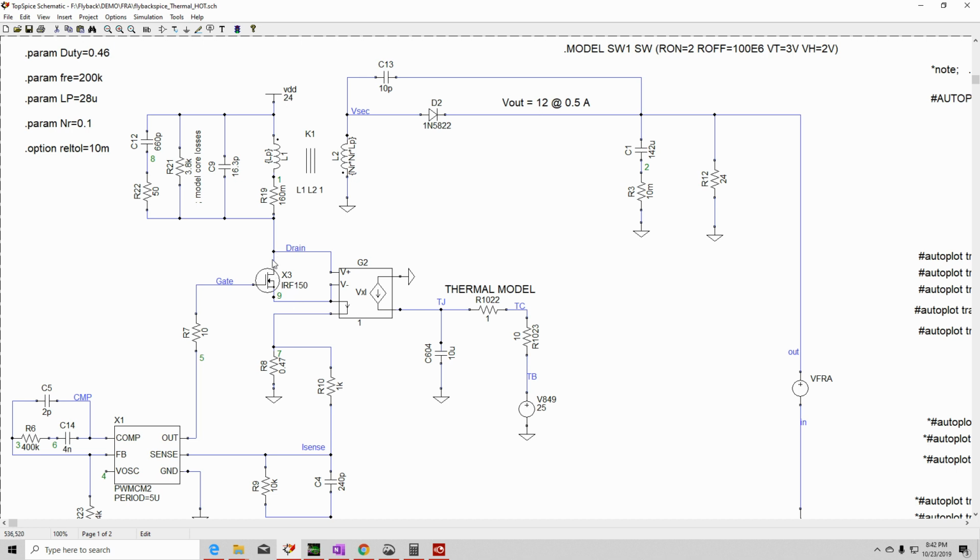Okay, so you also have a thermal path where the heat is flowing, and there's a resistance from the case to the board. Okay, and a typical number that I use at work is R theta case to board of about 10. So I'm just going to go ahead and put that here.